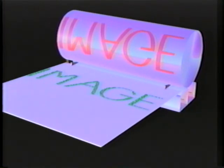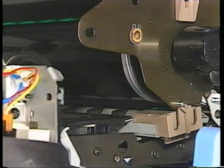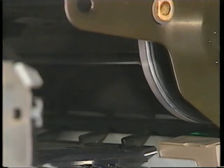We finally have something that looks like a copy, though not yet a permanent one. After transfer and separation, there's enough electrical attraction present to hold the toner in place until it's bonded to the paper. For successful transfer to take place, the electrical charges on the drum, toner, and paper must be suitably balanced. If there's too much charge on the drum, the attraction between latent image and toner is too strong for the corona to overcome, and the toner won't transfer completely.